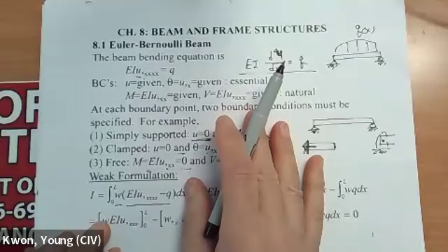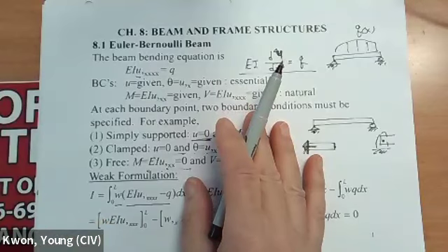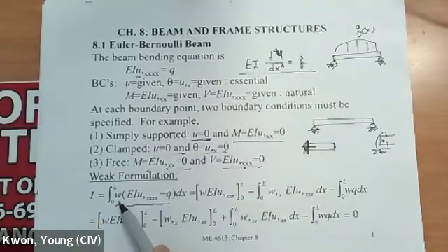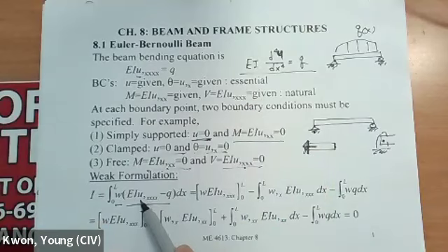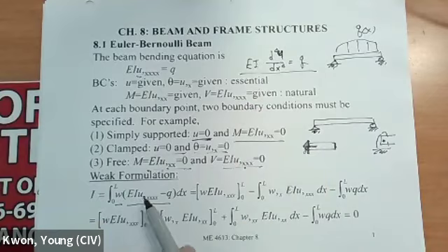In Galerkin's technique, W is the test function and U is the trial function, and we use the same function for test and trial. But this requires a fourth order derivative, while this requires a 0th derivative. So there is a mismatch of requirements, a very strong requirement. This is the so-called strong formulation.